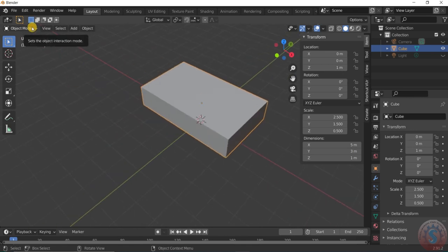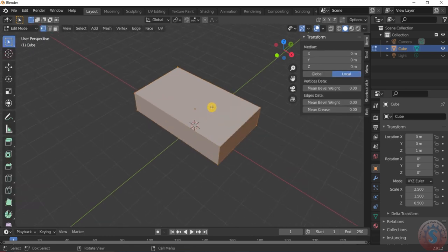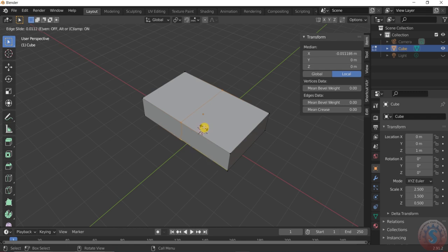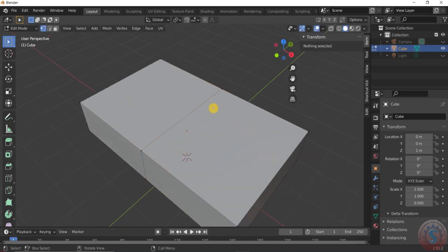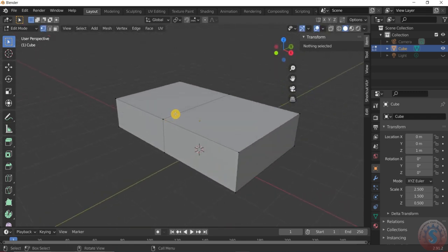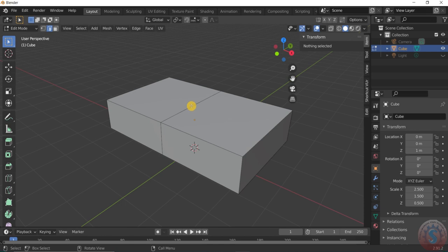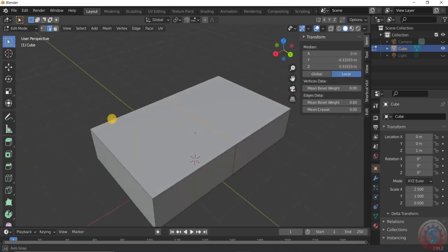Then I want to go to the edit mode here, select the vertices and use Ctrl R. By pressing the Ctrl R key, one loop is created. By pressing escape and the left key, the loop is created, you can observe. Then in the edit mode I select the edge mode and select all of the edges by using the shift key on the loop.